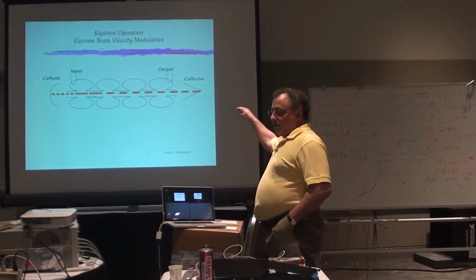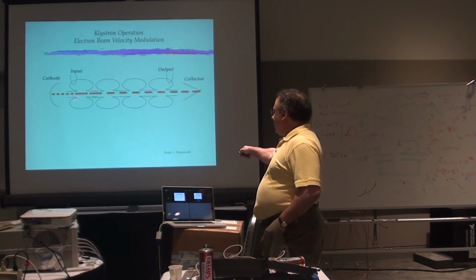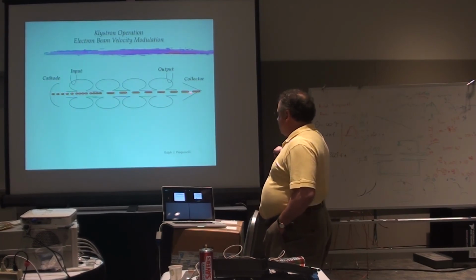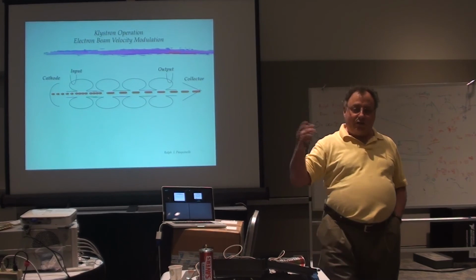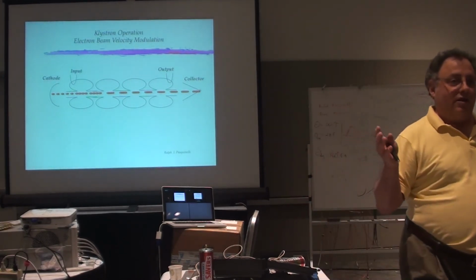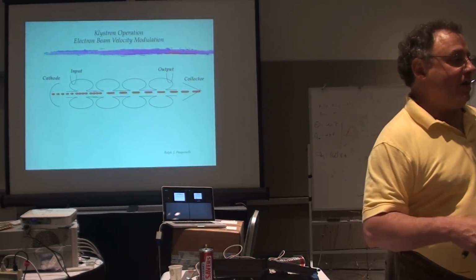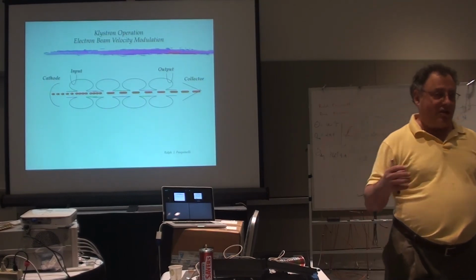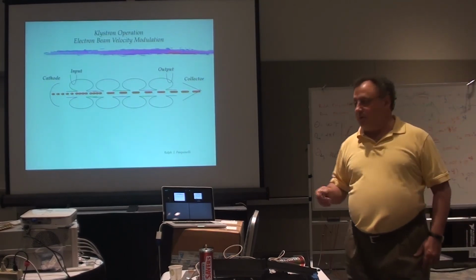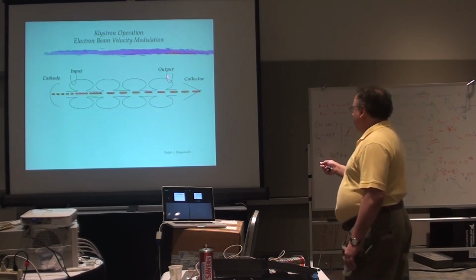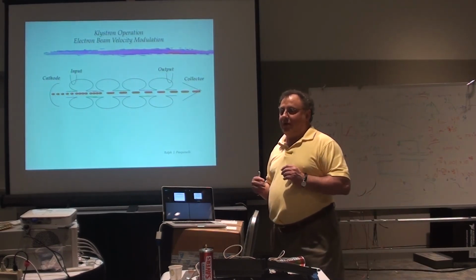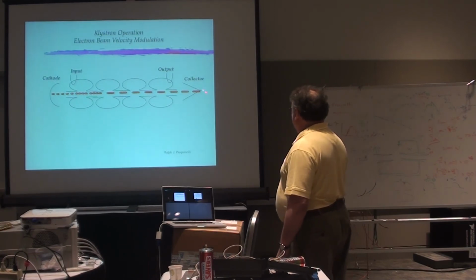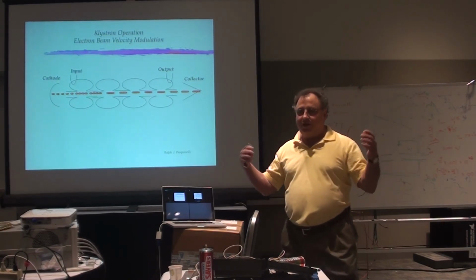And all along, of course, this took just a little bit of power to do it, but the beam itself, say you had a 10 kilowatt klystron, well, then you'd probably have a 20 kilowatt electron beam. And if you design it well enough, you can get a klystron to be 50% efficient, which means by the time it gets over here, it's going to take half the energy of the electron beam out. The rest of it crashes right into the collector and starts heating water.